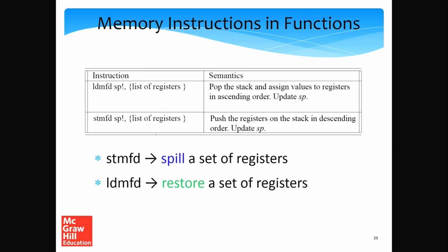So ARM has made this job easy. There is one instruction, STMFD, for spilling a set of registers and essentially saving them on the stack. Similarly, we have the LDMFD instruction to restore a set of registers. The format of both instructions is roughly the same.